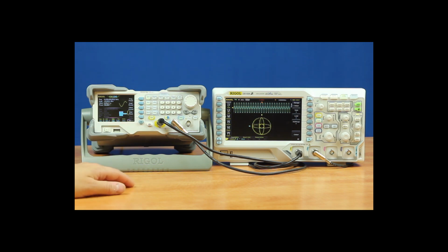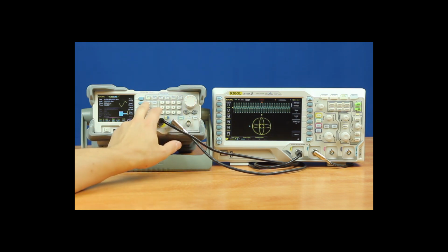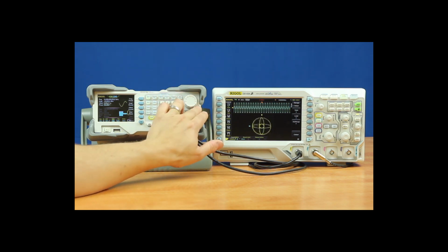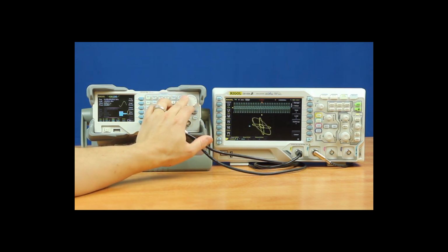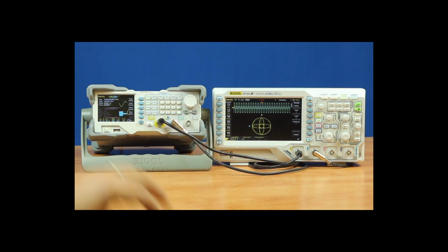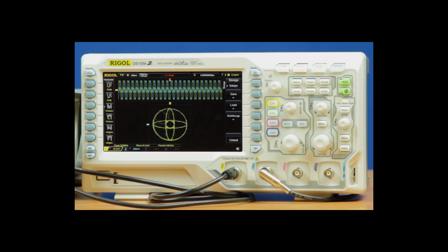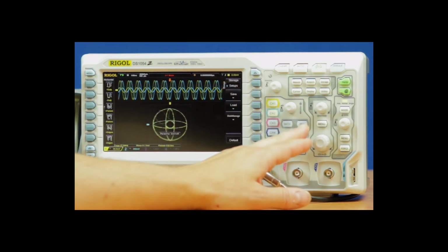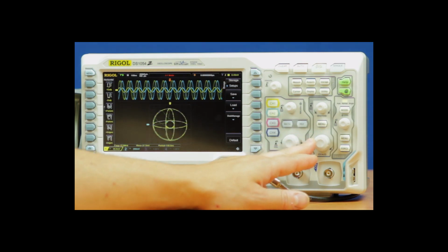to finalize this setup, you need to adjust the start phase by going to the sine menu, start phase on channel 1, and here we can adjust the start phase. The phase will not align directly because both channels are amplitude modulated, so you have to change the start phase until you get a nice round figure on the scope. And so let's look at what this represents. At the top we can see the time domain, and if we zoom in a little bit, we can see these two signals are 90 degrees out of phase.